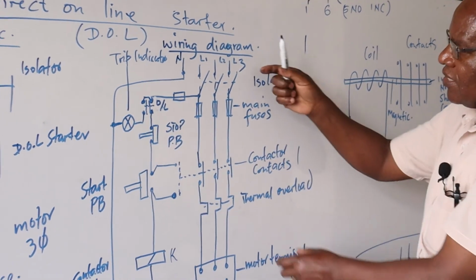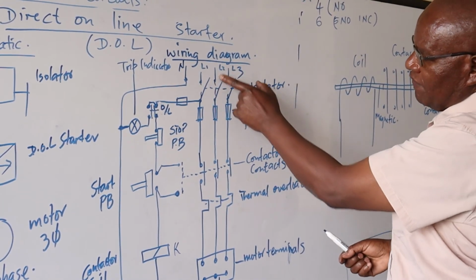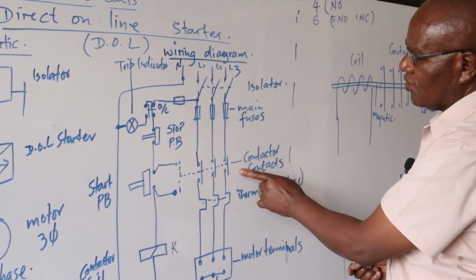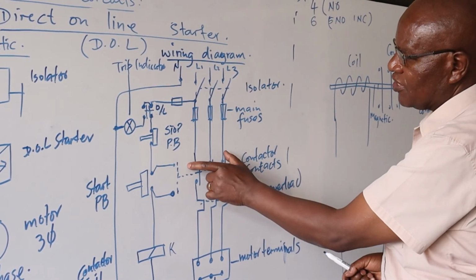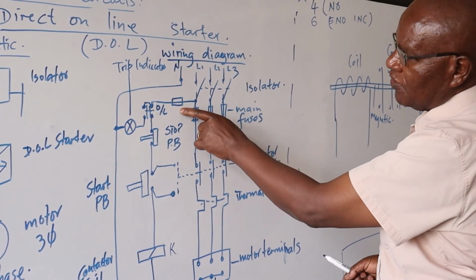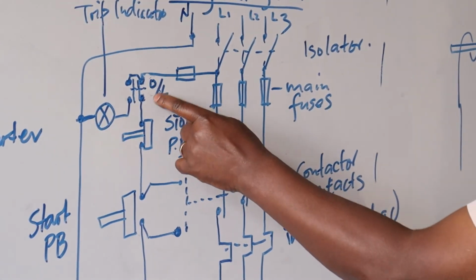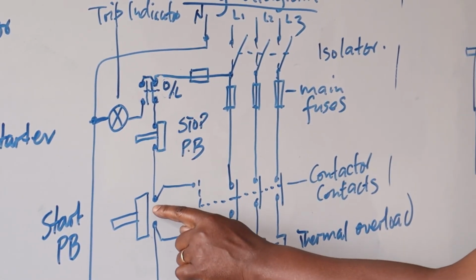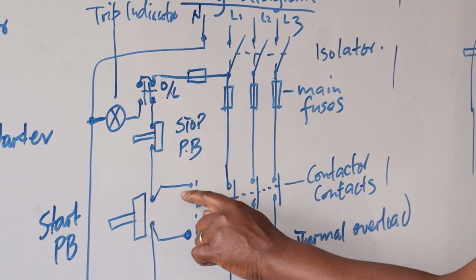And then you can see that when you move it there, the power will be available up to the top contacts of your contactor. And then on the control circuit, the power will flow through the fuse, the overload, the stop push button which is not pushed, and come to the starter on the top side of the contacts.